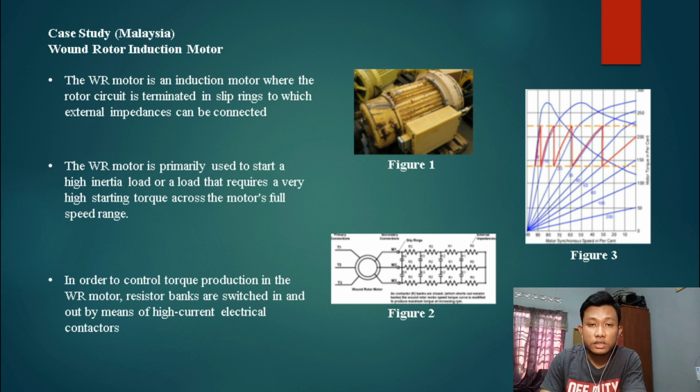So by applying a resistor to the motor slip rings, the motor is able to produce very high torque, which is 200% to 280% at a relatively low current, 175% from 0 to full speed. Relatively low locked rotor amperes are why these motors are sometimes employed in applications on weak power grids.